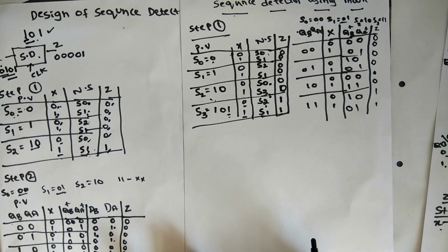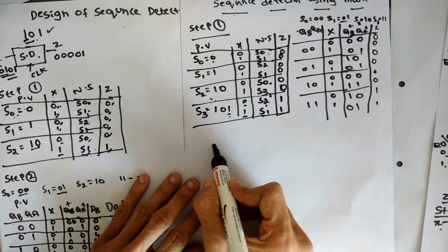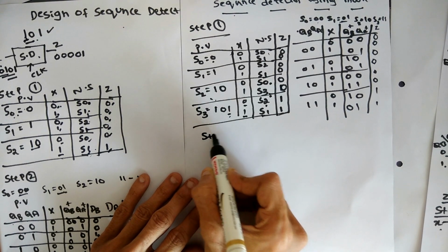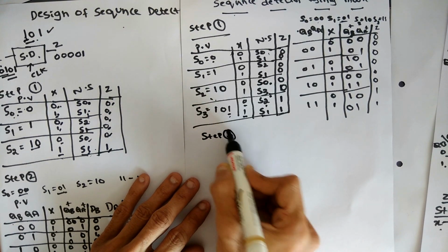If you want to write the state diagram of Moore, you have to consider two things here. The one thing is, we have to do it the same way as we did in the Mealy machine, up until the input sequence 1 0 has occurred, except that 0 output is associated with states S0, S1 and S2, and we have to take it for all three states. So first we can do step 3, the state diagram, and see how it looks.